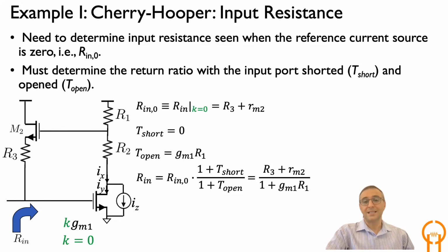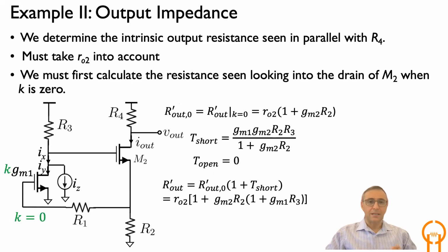And from this, you can easily see that this arrangement is lowering the input impedance. It is a shunt arrangement, which is lowering that. You can see the two currents are subtracting, if you will, in the input. And you can calculate the effective input impedance simply by the Blackman formula, which is shown in the last equation down here. So basically, this is an example.